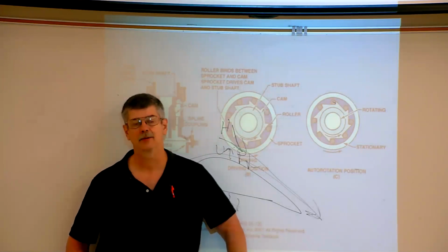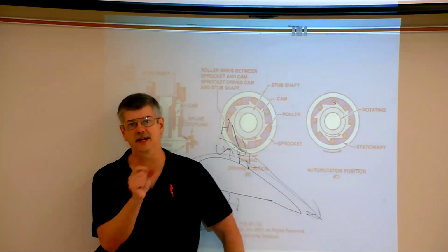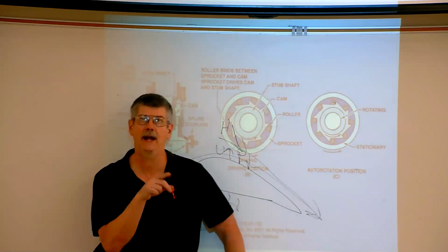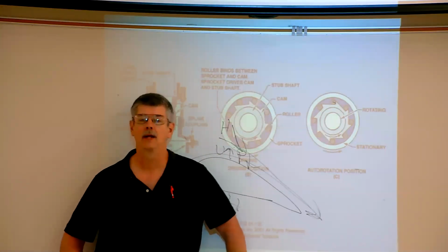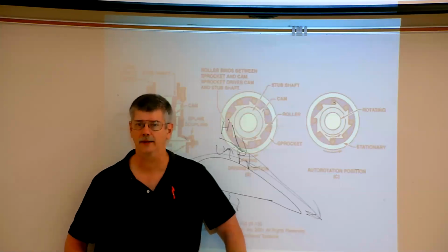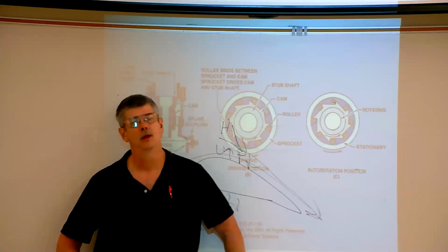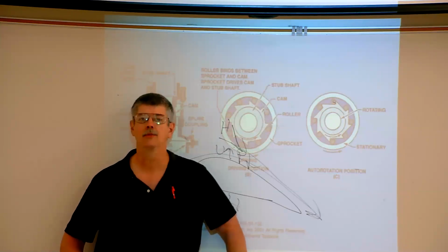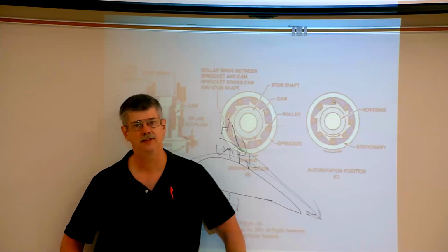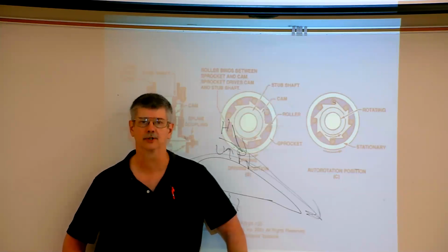And the dynamic pressure is actually 1/2 the density of the air times the velocity squared, times the area of the wing, okay? But the coefficient of lift is basically the aerodynamic shape of the airfoil, and the angle of attack is what determines the coefficient of lift.